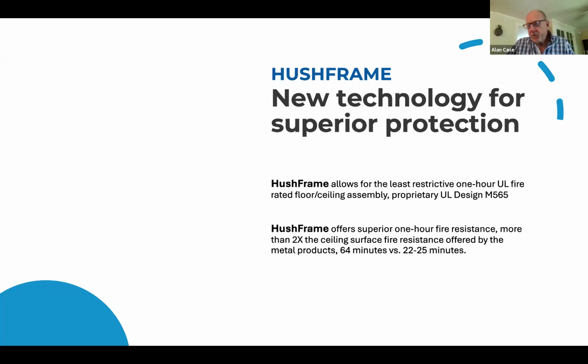So you get two tests. You get the fire resistance, which once you have the 60 minutes, you have 1 hour, and then you have what's called a surface rating, which is the time on the clock from the beginning of the burn till when the panel membrane on the ceiling first opens and allows that flame to enter into the interior of the assembly.